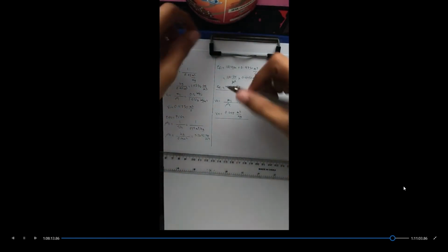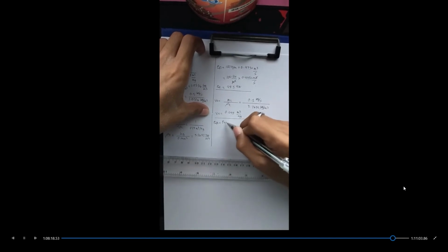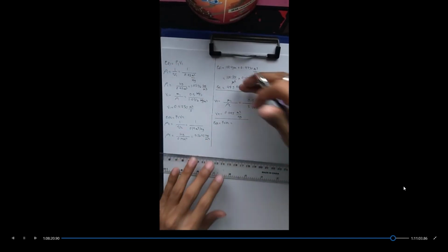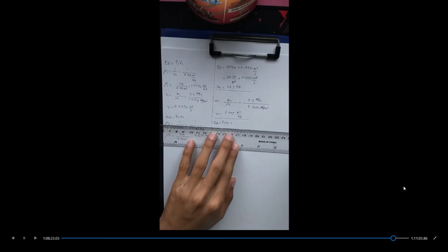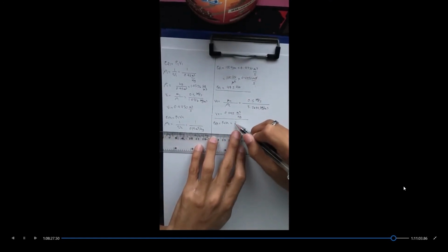And the next thing we would do is apply the formula for flow work 2, which is pressure 2 times volume 2. The same thing as what we did here on the EF1. So pressure 2 is given as 700 kilopascal.